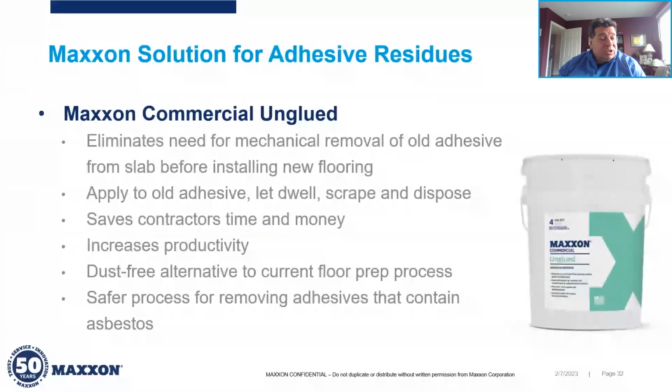So it's a dust-free alternative to a mechanical removal process. It's obviously going to be safer because you can remove it in either a wet or dry process, and the wet process would allow you to keep dust particles from getting airborne if it happens to be an asbestos-ridden adhesive.